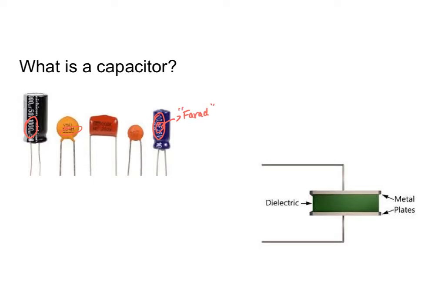But it's also important to know, guys, that a lot of our circuit components look pretty similar in real life. One key difference between a capacitor and a diode is that our diodes have two different length wires, since they have a positive and a negative terminal, while our capacitors, of course, have two identical wires. However, it can be hard to tell the difference, which is why it's important to zoom in. So here we are zooming in.